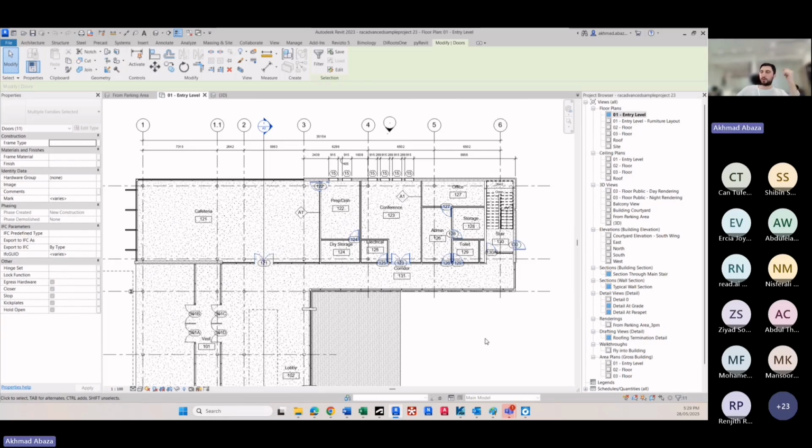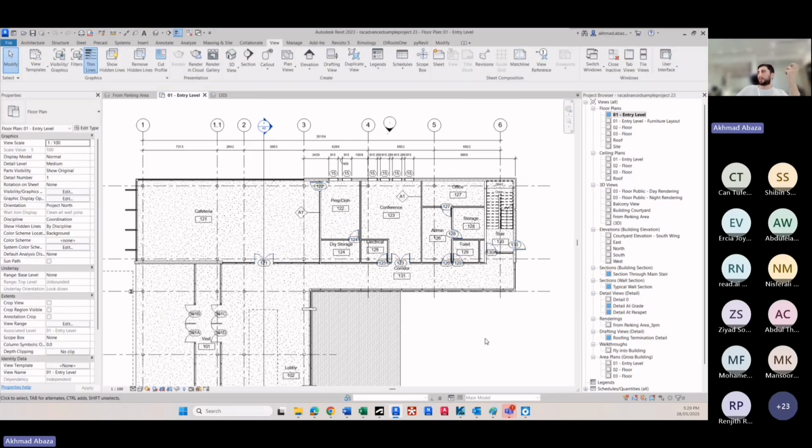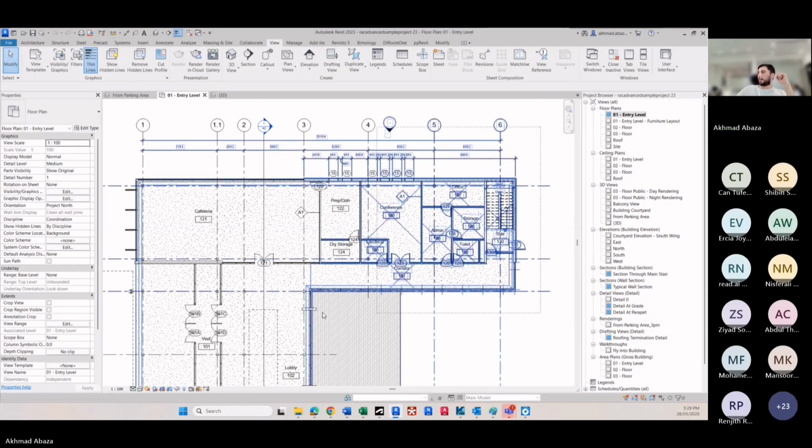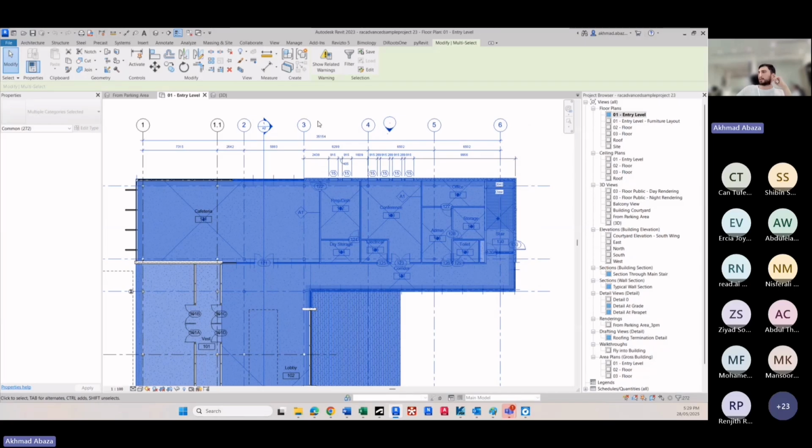For sure, we will not do this every time we want to select a category. So this is an important thing to understand: we can open a box like this, and there is an important tool in Revit called Filter. What does this filter do? It categorizes your selection based on the Revit category.